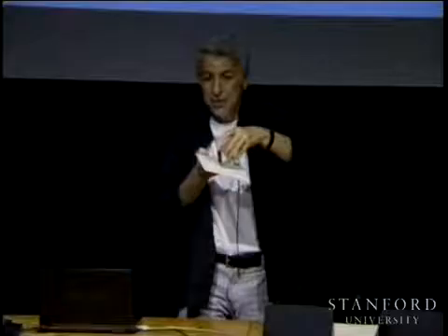Because in any assembly, you're going to have some error in the relationship between the two. How do you deal with this? How do you deal with the fact that when you are pushing down, you are going to have a moment generated? Well, you can use it to drive this rotation. And this reaction force here will rotate if you select this point as a center, as your operational point. If you push from here, it rotates. This will be fixed. You can fix it by controlling this point, and now you are rotating about this point.